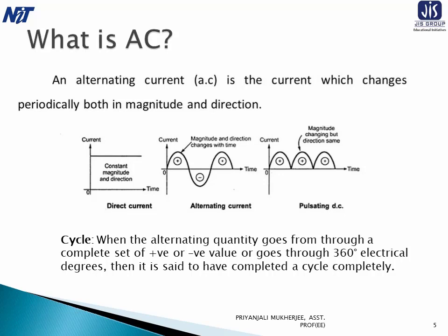For conversion of AC into DC, the DC generator as a part of a motor generator set has been replaced by SCR rectifiers and various other power control devices. These are usually cheaper in cost, compact in size, relatively noise-free in operation, and require minimum maintenance. Though they can suffer from some disadvantages such as poor power factor, harmonic generation, poor braking, like this.